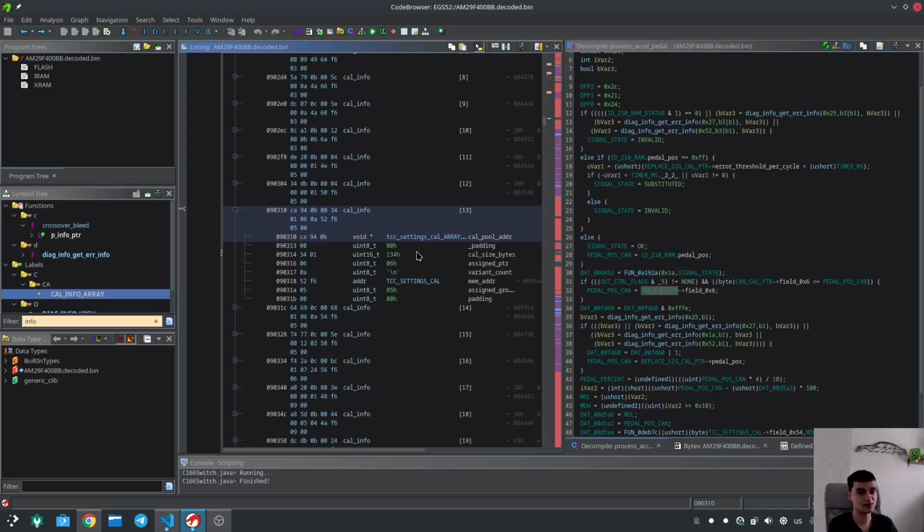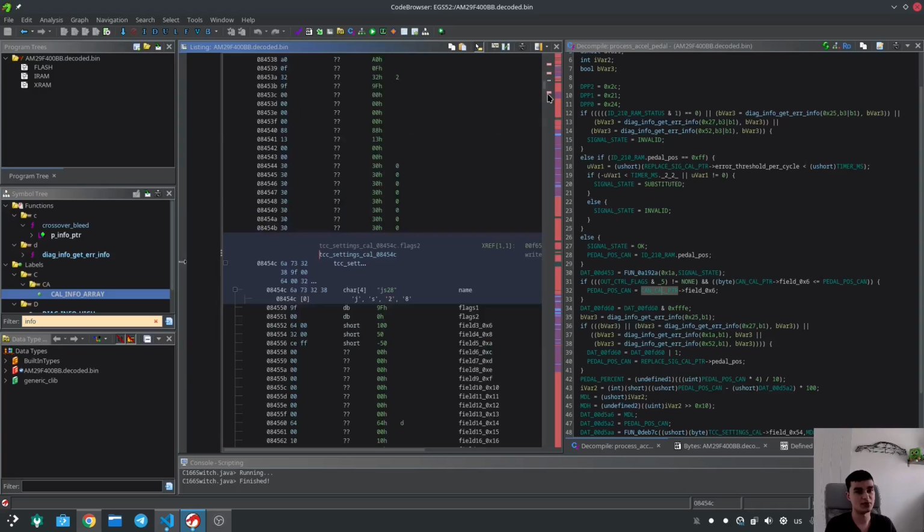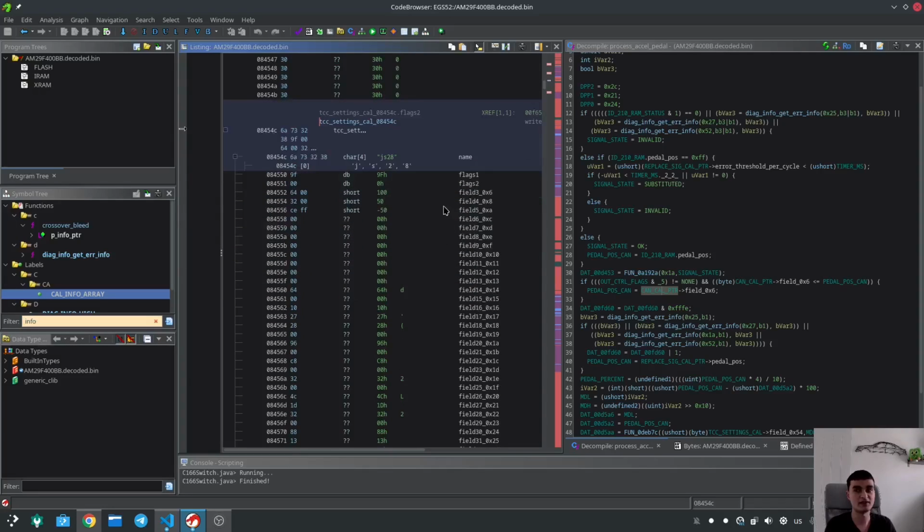So essentially this way they can hot swap one EGS part number into multiple cars, just change the SCN coding string which says select a different data model for each calibration type, and the EGS then actually copies this information to a pointer which points to a higher block of memory up here, where the one which is currently in use is stored. This has got something to do with the way that the C166 CPU does memory addressing. It's just more efficient if all of the calibrations are in one block at the top of memory.